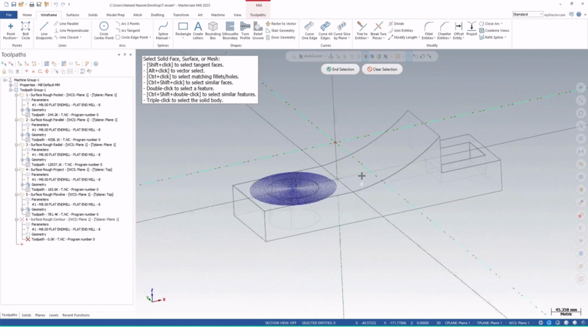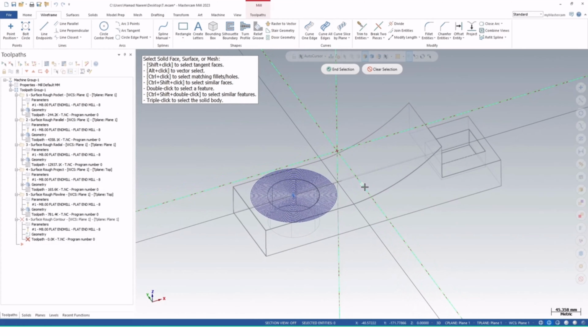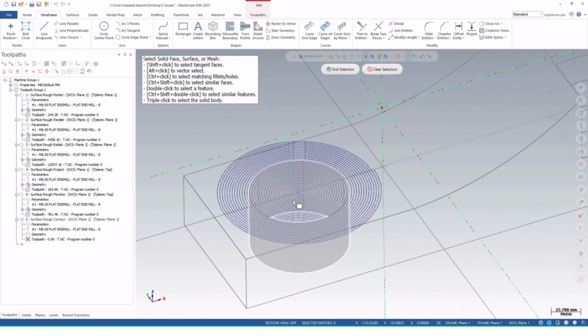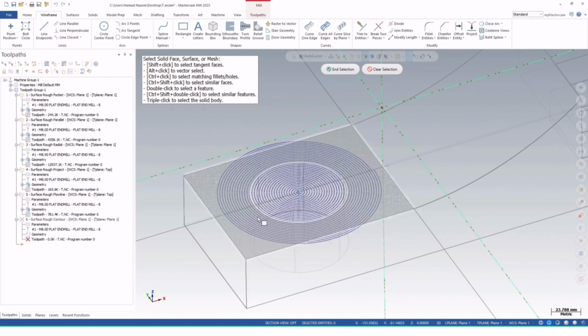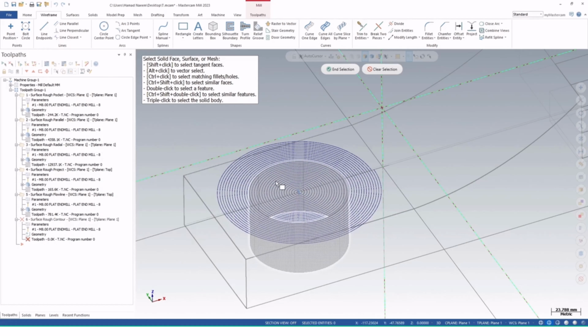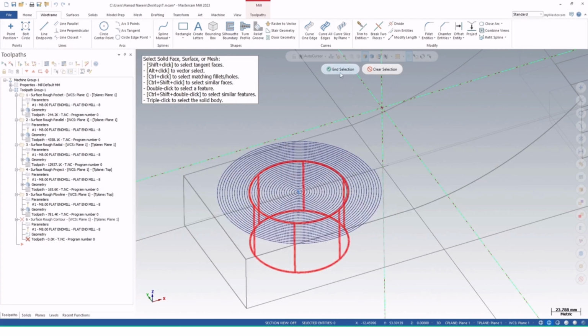If you want to do inside operations like this, we have the cavity here and we just want to remove that material. We have a hole and we just want to contour that surface area, or we want to move the cutter peripherally to this surface or tangentially to the surface. Then we use this contour area. Let me select this area and machine it.